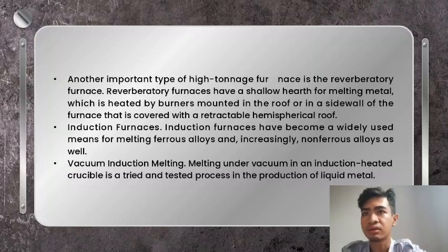Alternating current furnaces are favored for producing steel castings and typically have three large cylindrical-shaped electrodes that have a thread coupling on the end. These electrodes strike the electric arc that is used to melt the scrap material charged into the vessel. The electrodes float just above the surface of the cold ferrous scrap or molten bed and automatically move up or down to properly regulate the arc that is established for melting the charged material.